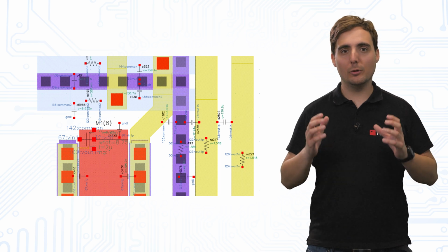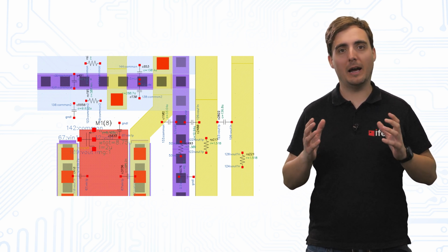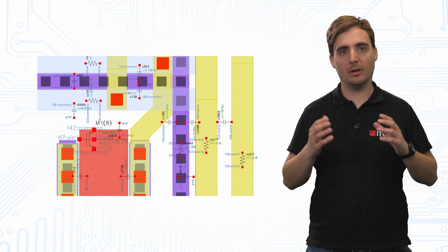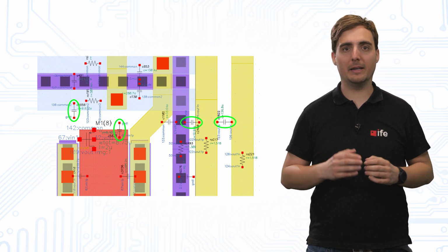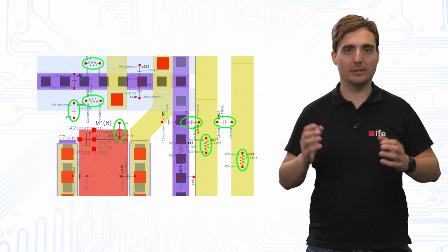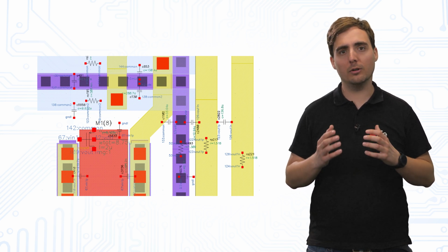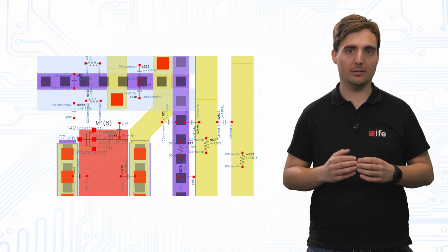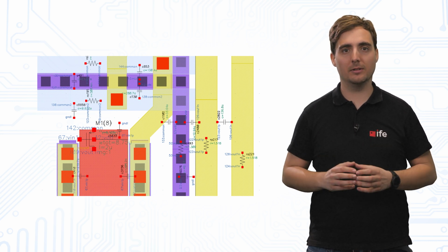Manufacturing a circuit brings up different parasitic components. These components are obtained by RC extraction. Among others, this includes capacitances to substrate, intermetal capacitances, path and gate resistors. Especially parasitic capacitances play an important role in EMI considerations, as high-frequency signals might be induced into other nodes.